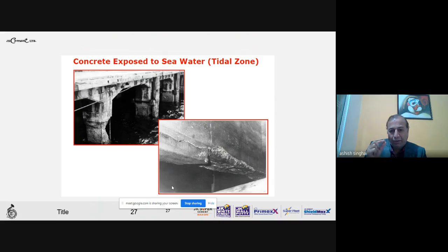As the volume of steel increases, stresses develop on the concrete. Concrete opens up, a lot of structural cracks appear on the surface, and a greater quantum of chlorides and sulfates goes into the concrete. That becomes detrimental to the health of the concrete, and as you can see in the pictures, a lot of spalling takes place, and the entire stability or structural strength of the structure becomes